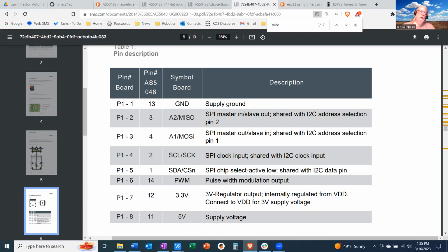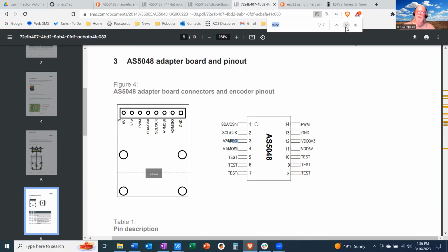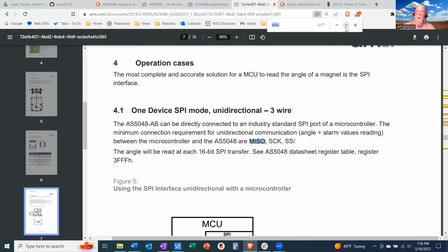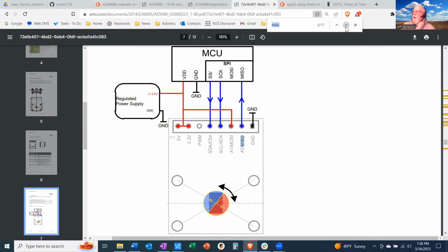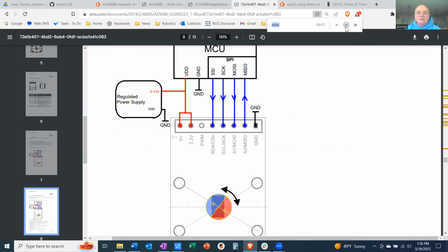Because I thought that at least the one that's in the Super Servo 200, whatever chip that is, has an I2C interface and it has one analog output, so you can read it either way. Is there some reason why you don't want to use the I2C? Nothing dramatic, other than I would think an interrupt-based detection would be more reliable than a timing-based interrupt, which is what I have now.